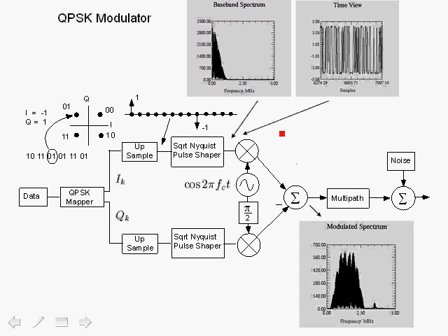And here we show the signal in the time domain, where we have a superposition of impulse responses of the symbols +1 and -1 that are the possible values for I sub k, and as before we can actually form the eye diagram, and we have 0 intersymbol interference at this point because we are using Nyquist pulse shaping.